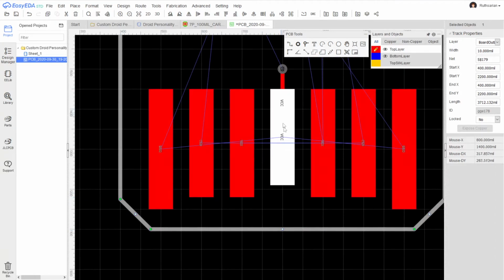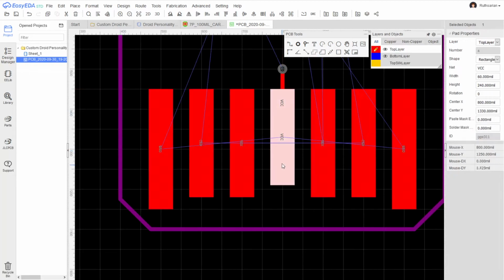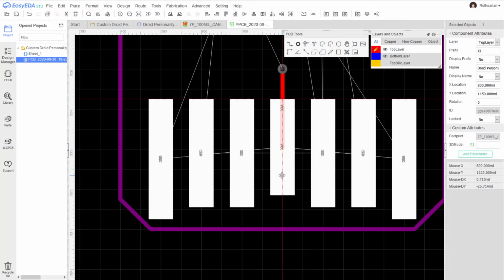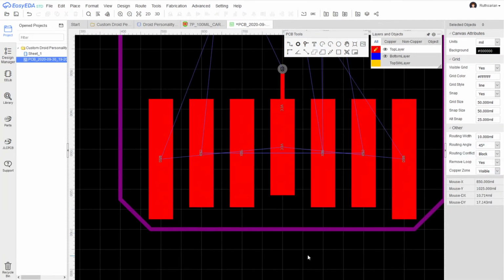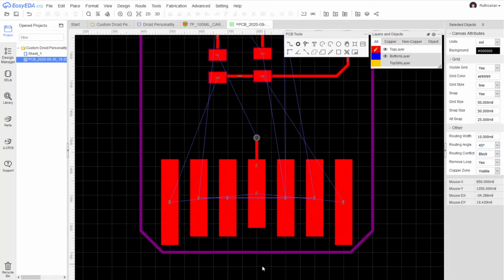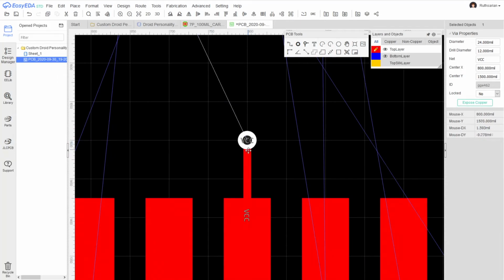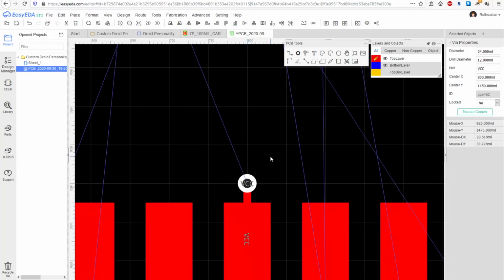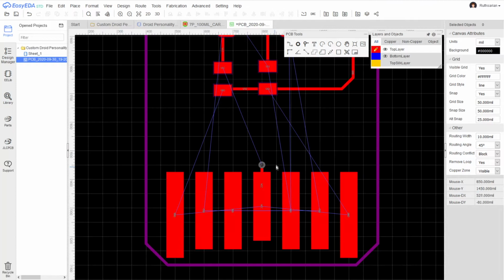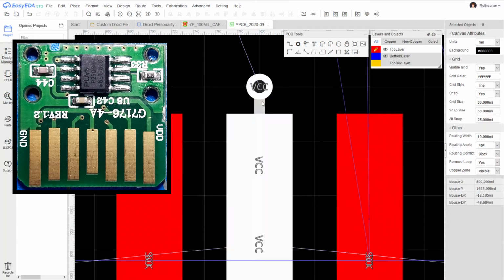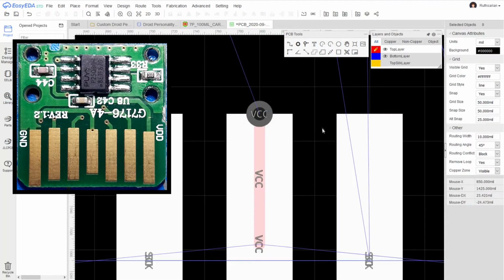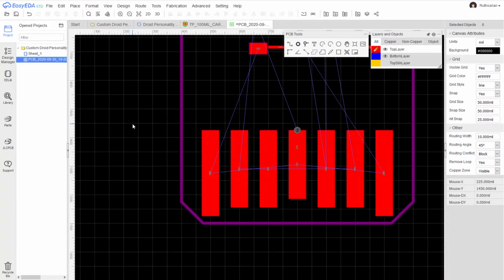And by doing that, I can bring down the gold fingers, run them a little closer to the edge of the PCB. And then if I want, I can move this via down too. It doesn't have to be all the way up there. In fact, if you look at the stock PCB, this via is actually about right there. And we could put ours there too.